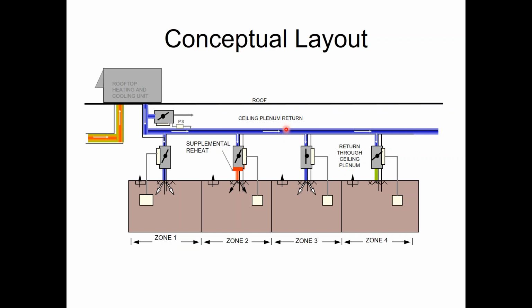I want to just provide enough pressure to get the airflow, in this example here, to this last zone on the end, zone number 4, because he's going to be the one that needs the most static pressure. In other jobs, it could be different. I might have zones that go left and right. I may have one with a weird duct system that has too many elbows off it, right? This guy right here might have had 17 elbows right here on zone 3. Okay, well now he's the worst zone instead of zone 4. But on this drawing, zone 4 is the worst.